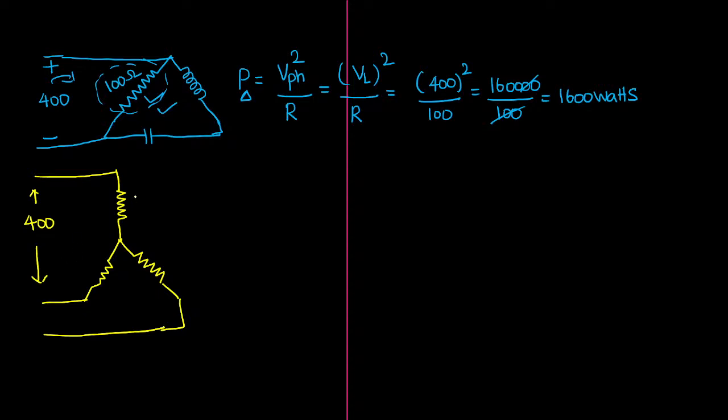And here they told that this resistor value is REX, the external resistor, right? So when we connect the star connection across the 400 volts, this will be consuming the same power. But in the previous case, in the unbalanced load, only one branch was consuming real power. In this case, all have the same value and are equal to each other, that is a balanced load.